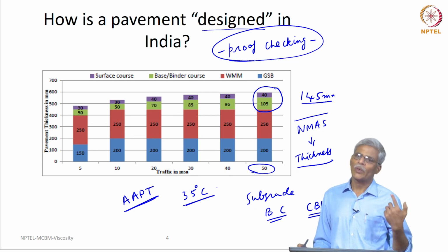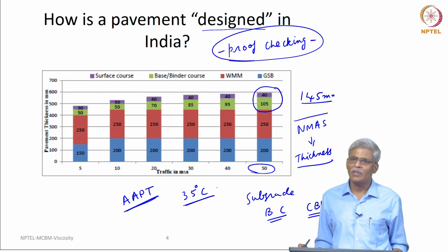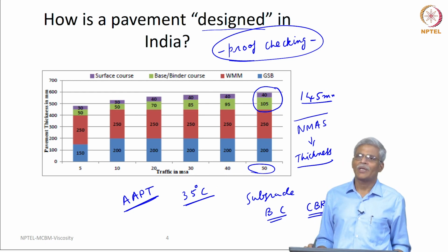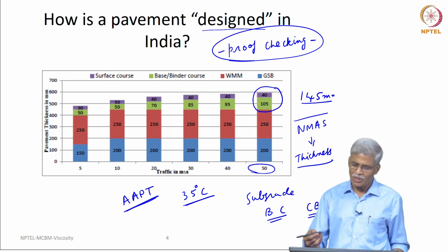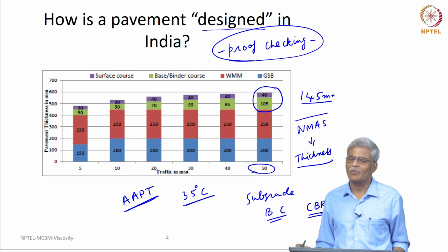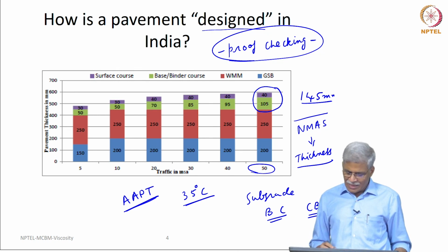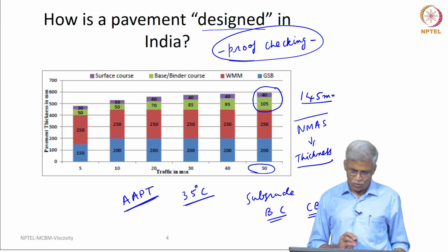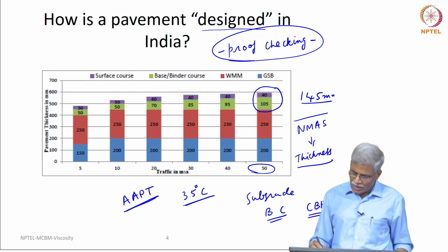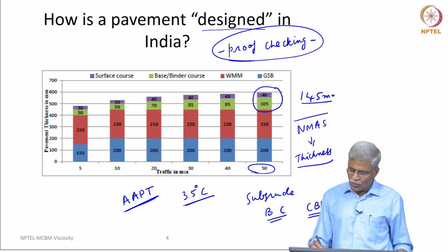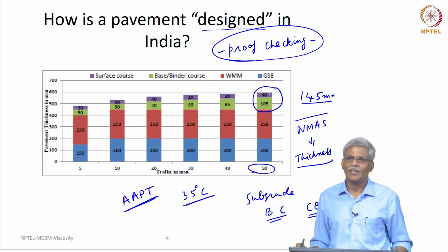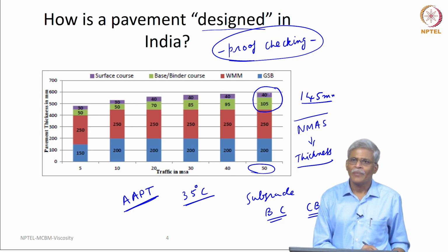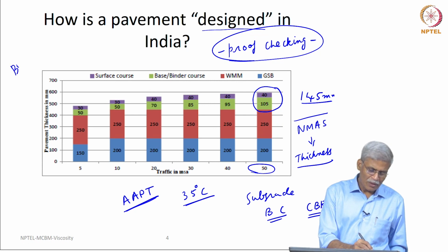So, depending on the location in which you want to construct your pavement as well as the traffic that you are expected to get, you are required to design a new cross section, design in the sense in which I mentioned, and check it, and these are sample templates that are given for us to use. So, as soon as we take this thickness, we need to use the appropriate material properties and check for the occurred fatigue damage as well as the rutting, and this is where the binder plays a critical role here.